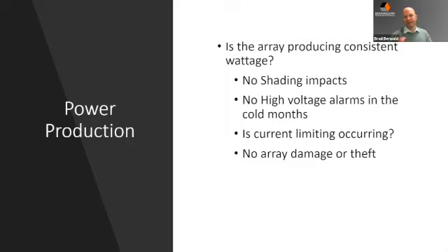So with that data, there's a lot you can view. When you start looking at day over day changes in the system, you get a sense of the behavior of the site. And when you look at weeks or even a month time period compared to a seasonal change, such as winter versus summer, same system, hopefully same loads, same PV array, but what is the impact of the cold climate, the low temperature on the battery, the decreased solar production?